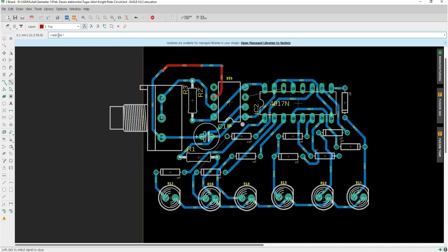Why? By knowing this information upfront, you can set your trace width and spacing values in your design rules and avoid having to reroute your entire board layout down the line. And by using trace width and spacing that your manufacturer can produce, you'll make everyone's life easier when it comes time to make your board.